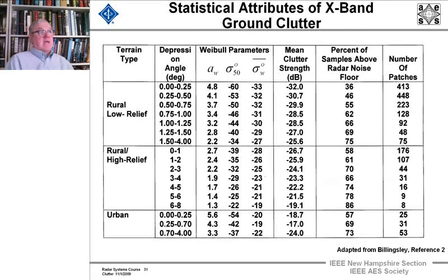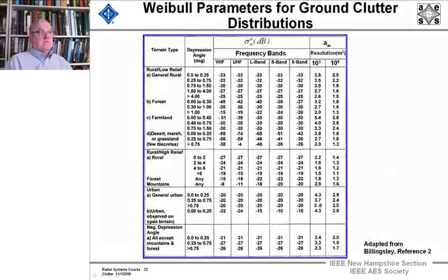So when you take that data and you fit it to the different distributions, you can come out with Weibull parameters that can be used to model that data. And all this is taken from Billingsley's work in reference to. And here are the Weibull distribution parameters.